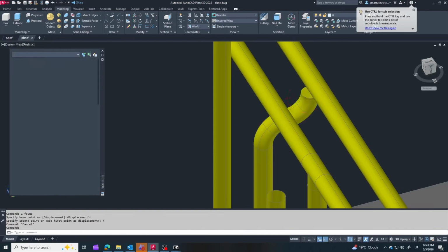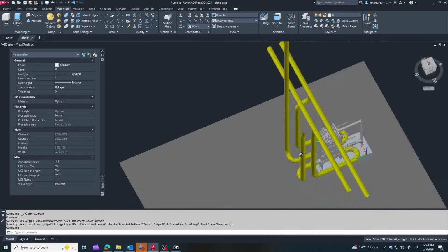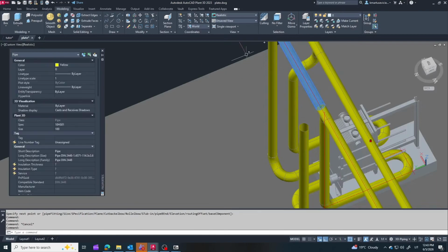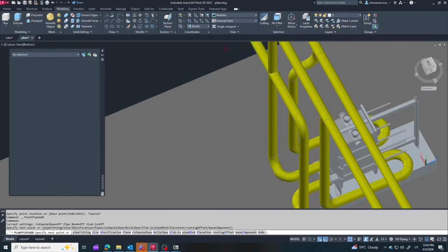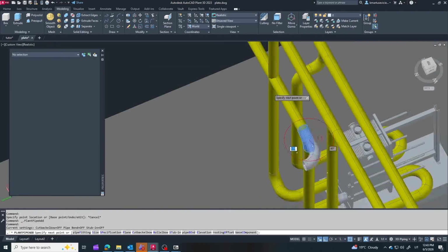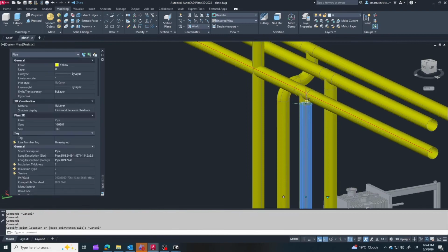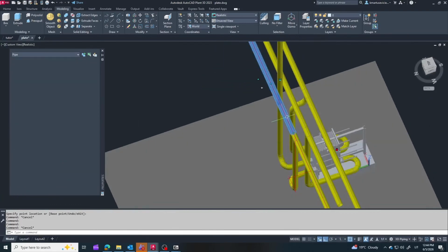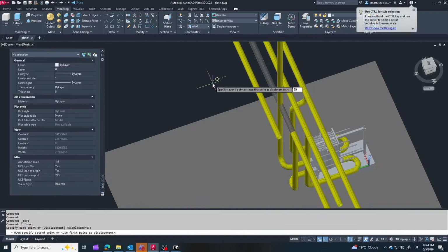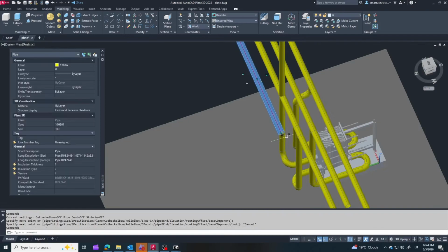Let's briefly touch on how a plate heat exchanger actually works. Inside this frame, we have a series of thin, corrugated metal plates packed tightly together. Channels are formed between these plates, and the gaskets direct our hot and cold fluids to flow through alternating channels. This layout gives us a massive surface area for heat transfer in a very tight footprint, making these units incredibly efficient compared to old-school shell and tube exchangers.